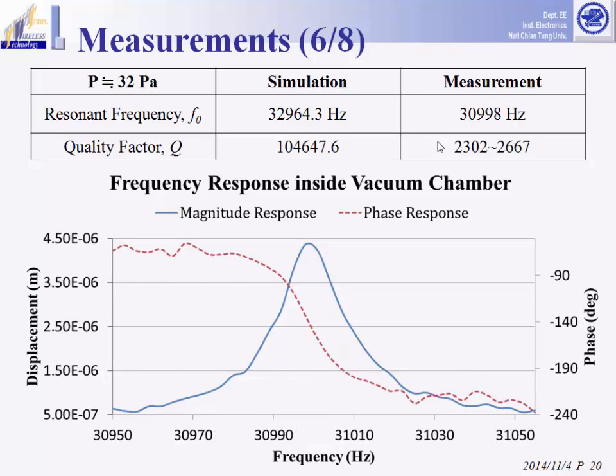Here we may notice the huge discrepancy in quality factor. The reason might be the vacuum chamber being full of oil molecules from the oil rotary vane vacuum pump, which will greatly degrade the quality factor.